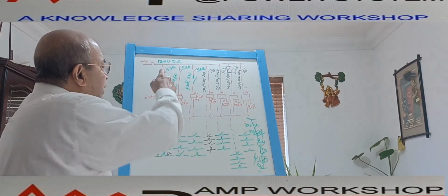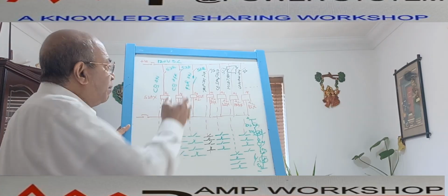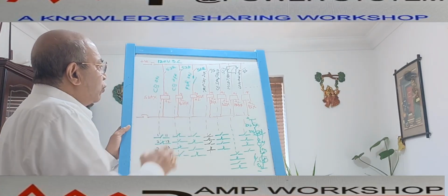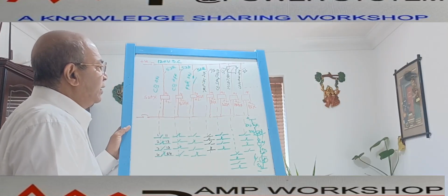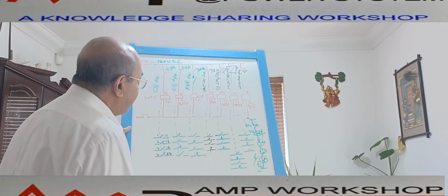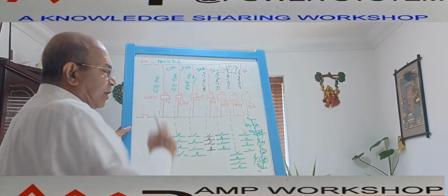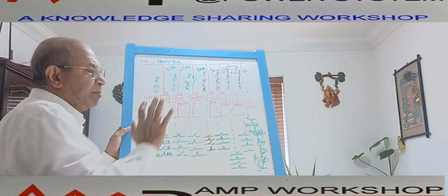When the breaker is closed, this 52A is a NO condition, and when the breaker is open, 52B is a closed condition. So if we use 52B, what does it indicate? The breaker is in the off condition, because when the breaker is off, this 52B is NC. So 52B being NC means the breaker is off.